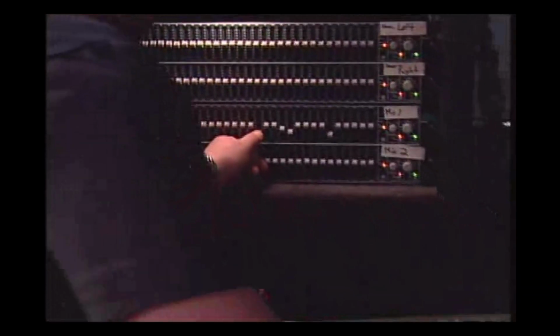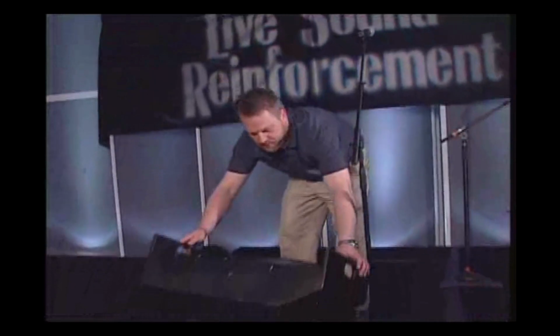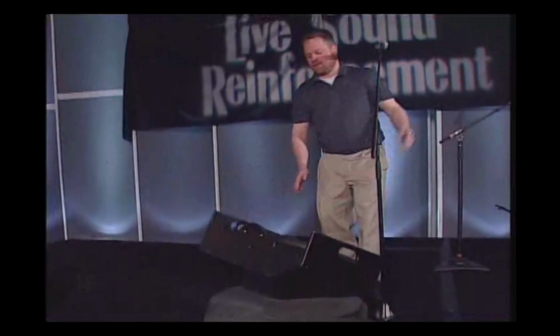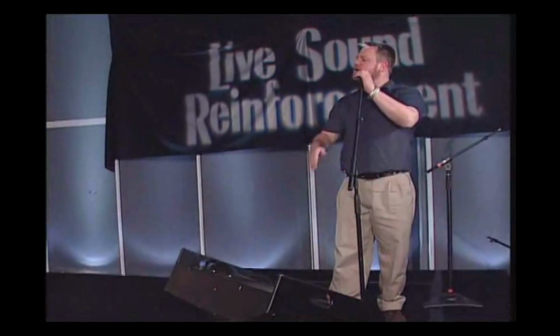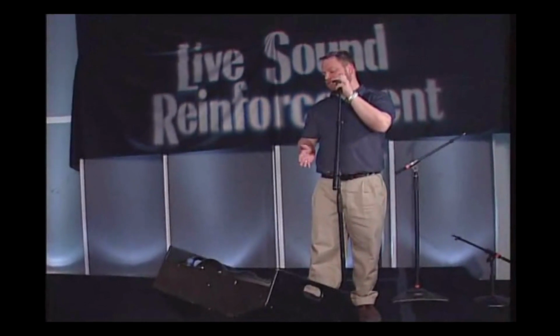The first thing to do is make sure you ring the monitors out correctly. That'll go a long way towards allowing you to raise the gain before feedback. Secondly, if you're using a cardioid or supercardioid mic, move the wedge to the side of the vocalist so that the axis of the monitor is close to the angle of minimum pickup of the mic. So knowing the pattern of the mic is important.